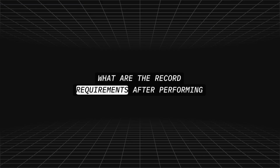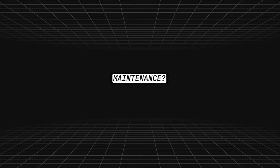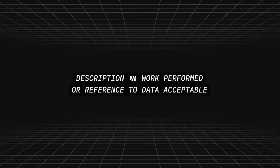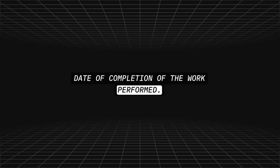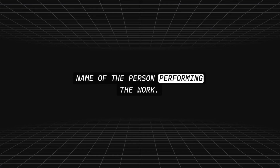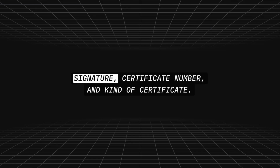What are the record requirements after performing maintenance? Description of work performed or reference to data acceptable to the administrator. Date of completion of the work performed. Name of the person performing the work. Signature, certificate number, and kind of certificate.